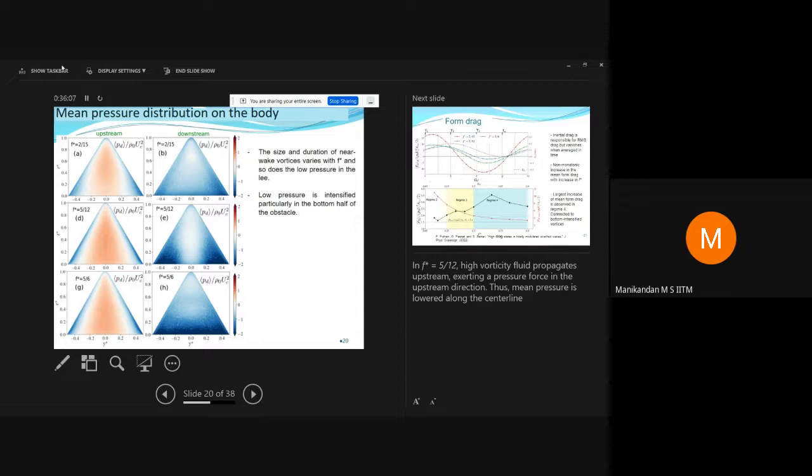The Strouhal number of 0.26 that we saw is perfect for a 2D cylinder. So the frequency looks like a 2D cylinder, but if you look at the structure of the flow, it is different. A 3D roughness element, but without stratification.